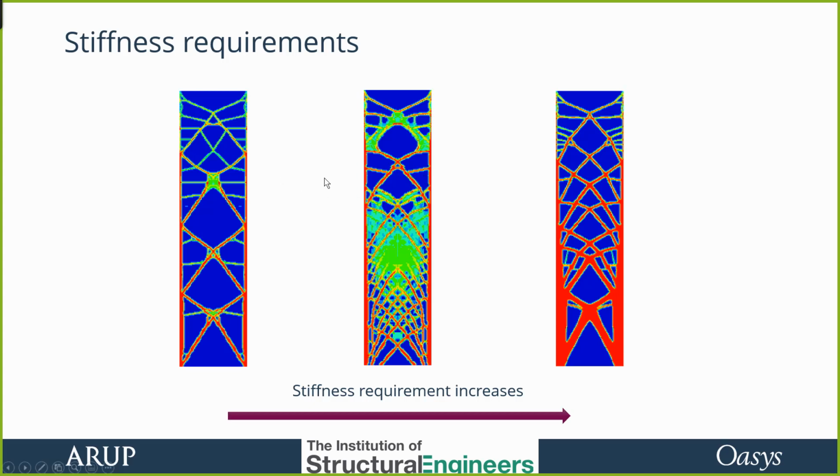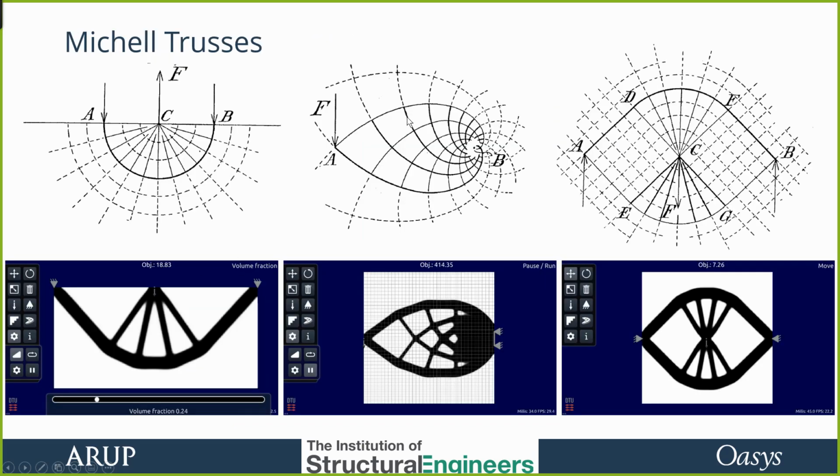You'll also note, and also go back a slide, one of the significant things about these Mitchell trusses is they often feature right angles. There tend to be right angles at each of these connections, and a feature of optimum trusses is the forces have at least the minimum sort of change of direction in them.